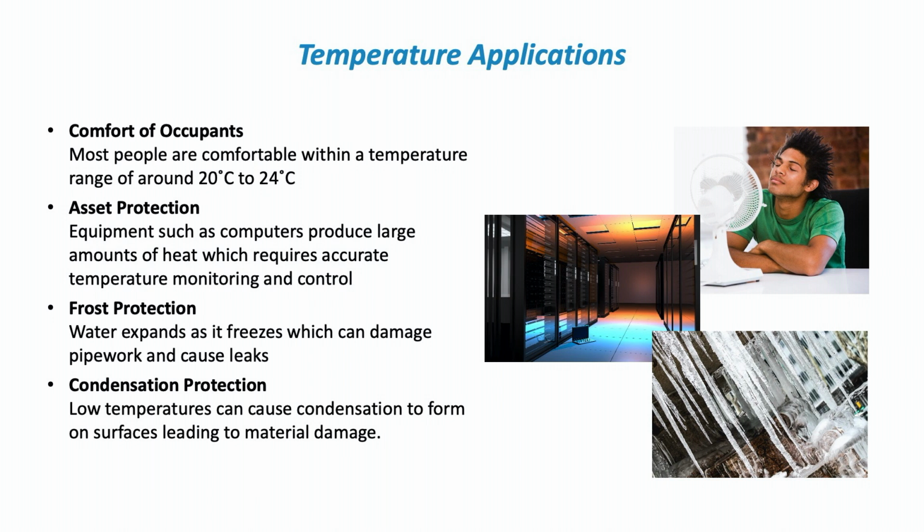And we also have to think about frost protection, which is a temperature control application. Water, unlike most things, expands as it freezes. If you imagine a tray of ice cubes, you put them in the fridge. When you put them in, the water is level. When you take them out, you've got little domes of ice because the ice has expanded. If that ice is in pipes in your systems, then that expansion can cause the pipes to rupture. So we look at outside air temperature, we look at various temperatures of the water going through the building, and we operate our plant to protect against those freeze events.